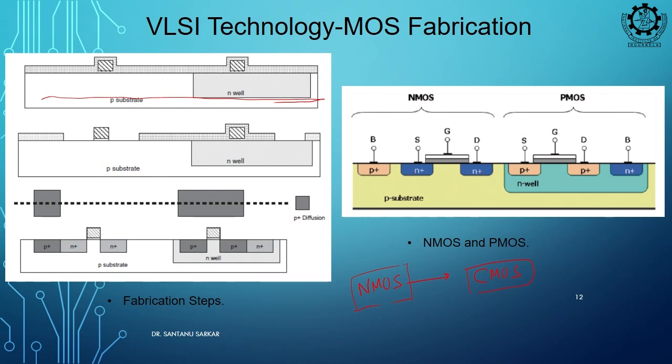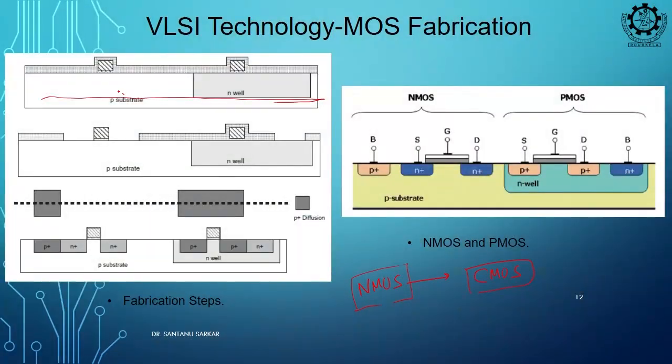This is my silicon. Now, when you are making an IC you need some pin also, right, for the physical connections. You need to give some connections, source, drain, gate, when you draw a circuit. So, this is your silicon, first level is P substrate, on top of this you will be making a window of N, right, another window of N. So, one becomes source, another becomes drain, right.